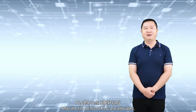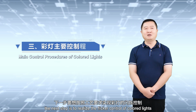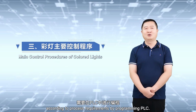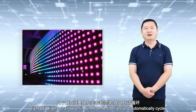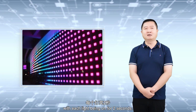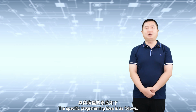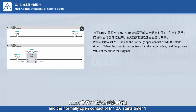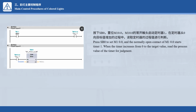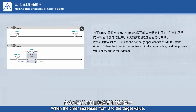After the I/O points of PLC are allocated, the next step is to realize the flicker control of colored lights according to process requirements by programming PLC. According to the control requirements, 8 LED lights shall be on in turn from left to right and automatically cycle, with each light being on for 2 seconds. The specific programming idea is as follows. Press SB0 to set M1 0.0, and the normally open contact of M1 0.0 starts timer 1. When the timer increases from 0 to the target value, read the process value of the timer for judgment.